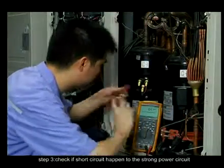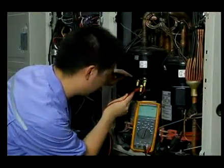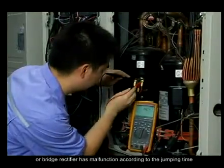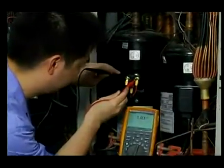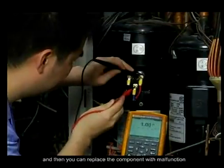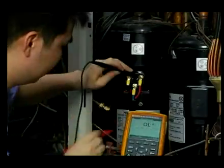Step 3. Check if a short circuit has happened in the strong power circuit. You can roughly judge whether the fan motor, compressor, reactance, capacitor, or bridge rectifier has malfunctioned according to the jumping time. Then you can measure the resistance one by one to see if it is open or infinite, and then replace the malfunctioning component.